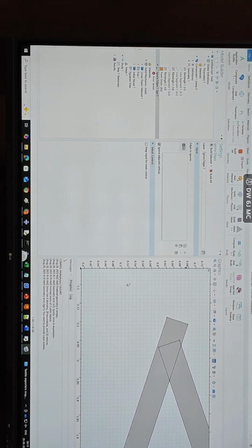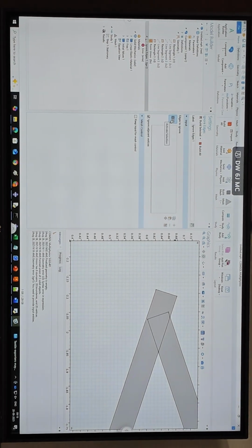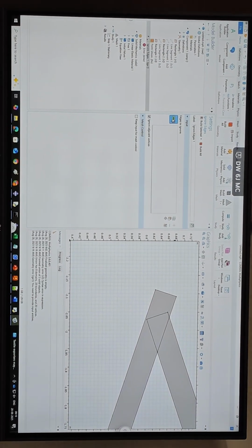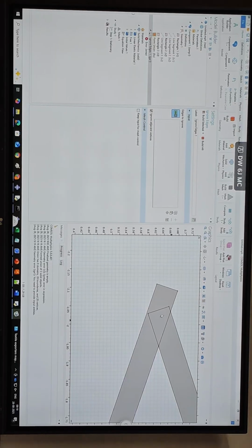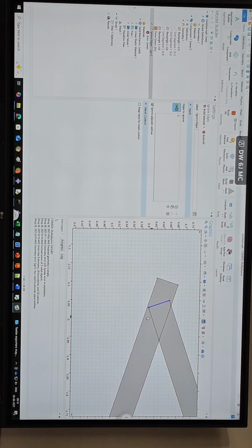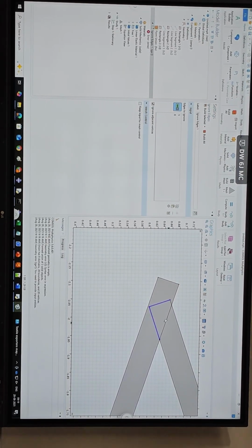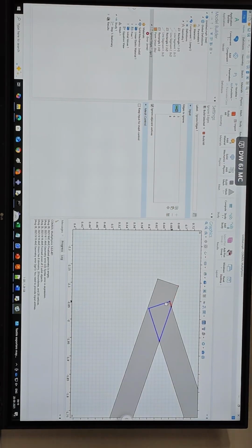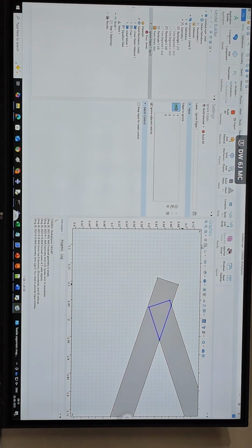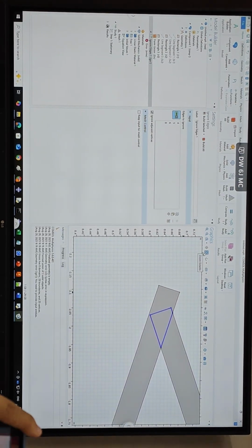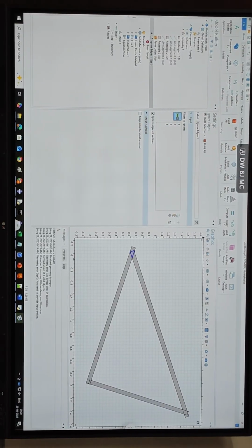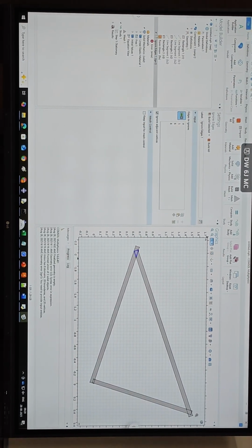Okay, don't worry about this. So now in ignore edges, first you activate the selection. That's that left icon. It becomes green. Then you can start selecting the element edges you want to remove from the connection. So say I want to remove these edges from the connection. Anything which is within the gray region can be removed. So we go here.